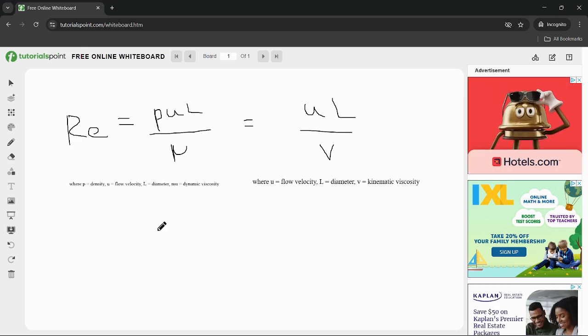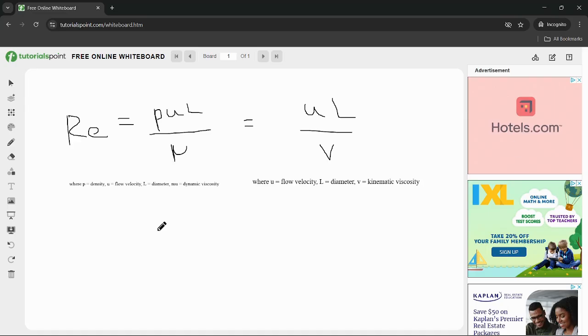So if we wanted to calculate the Reynolds number and entrance length for our simulation using the properties I set, we'll use this equation first. So flow velocity 0.01 is the inlet I chose. The length or diameter is 0.004, I believe.